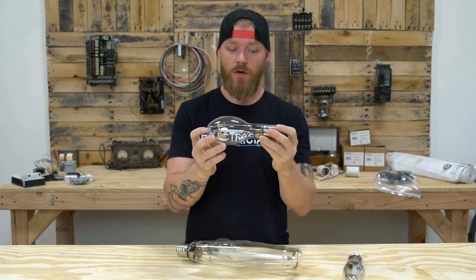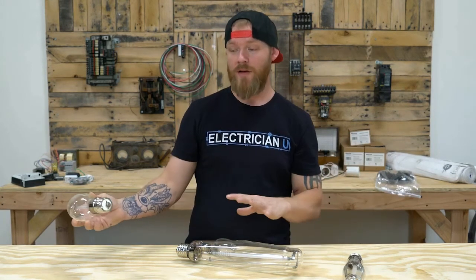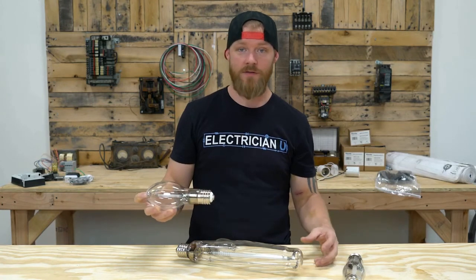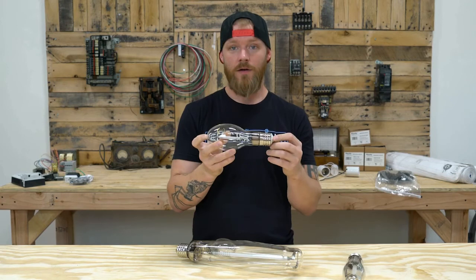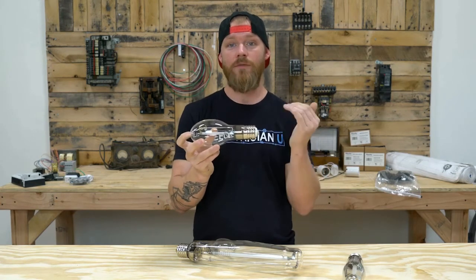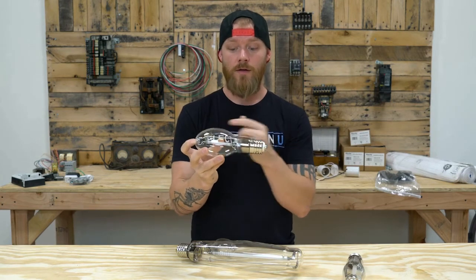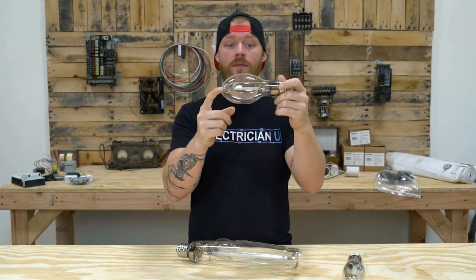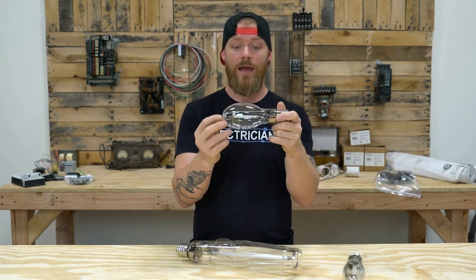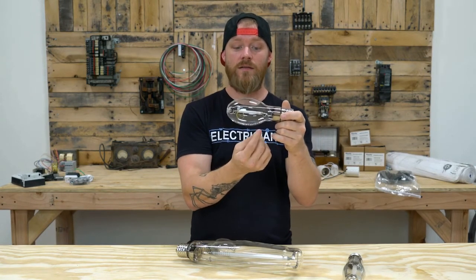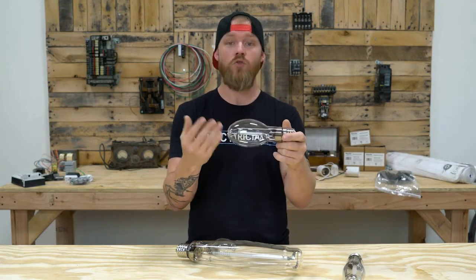So the process for how this works is the ballast outside of here actually has an igniter. A normal metal halide fixture is not going to have an igniter to it. That's how you can tell the difference between the two ballasts when you're looking at them. That igniter, once current is run through it, sends a high voltage pulse of current through the lamp to strike an arc. So the base gas that's inside of the tube is xenon, and then there's two other types of gases that are created once the heat inside of the tube rises.